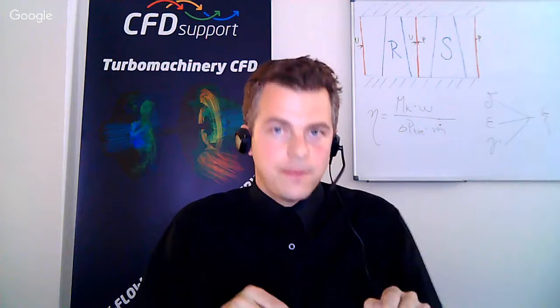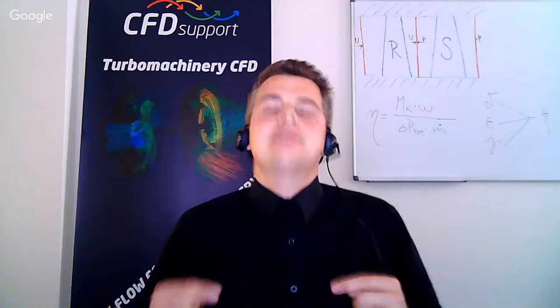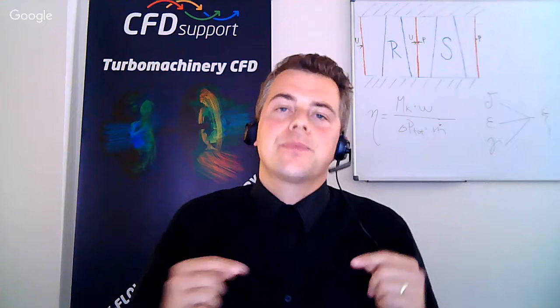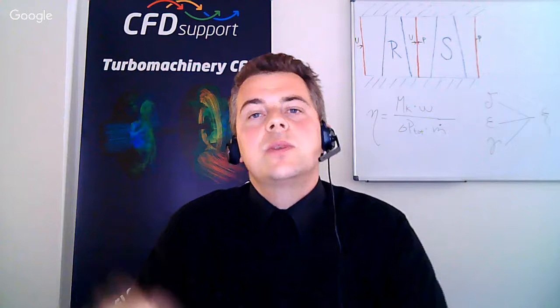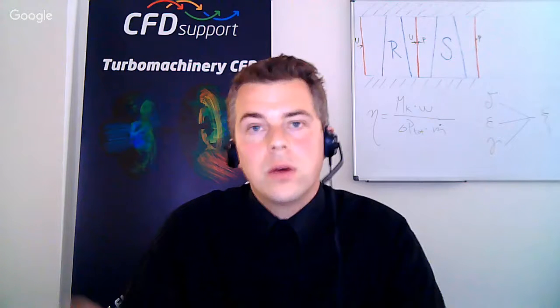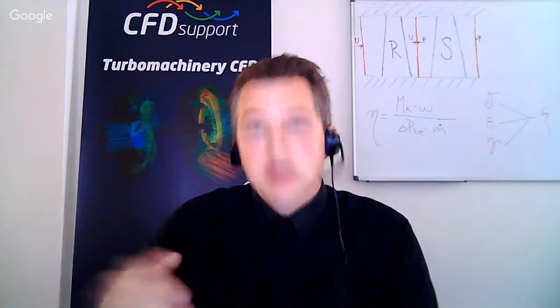And no, in the graphical interface you can't select the turbulence model. It's easy to do that, but it's not yet available in the graphical interface. So it's possible in the command line, just manually. You can create your case, then you switch to K epsilon, for example, or to some low Reynolds model, and then you run the simulation. That's okay. But in the graphical interface you can't.